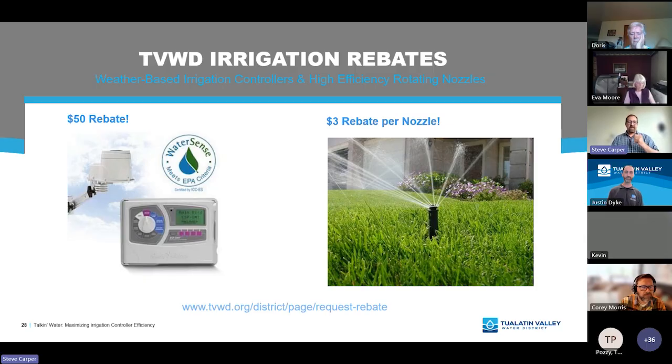Yeah, so if it continuously gets clipped by a lawnmower, it could be a couple different things. So here's your sprinkler head. I wonder if turning off, you guys can see that. I can see it all right. So the top of the sprinkler head should ideally be right at the top of where the mulch or compost is, if it's in a garden flower bed type setting, or if it's in the turf, it should be at the top of the soil level, basically.